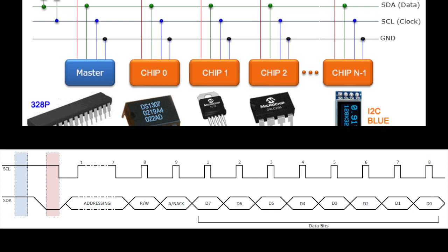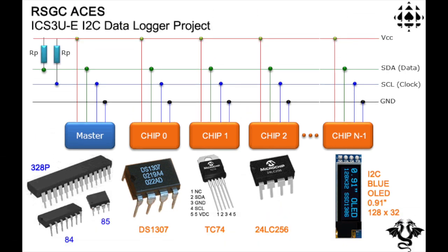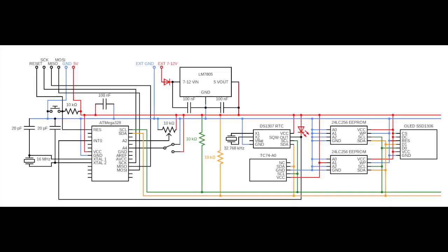Then, communication between the peripheral and the controller continues while the rest of the peripherals go back into their resting or dormant phase. Communication continues with the clock pulse running, and then 8 bytes transferred along the data line with an acknowledgement on the other end of the transmission reception. After the transmission cycle is complete, the master stops running the clock pulse and the transmission between the peripheral and controller ends.